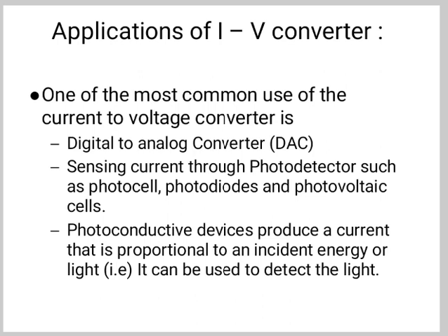Second is measurement of a photoresistor. This type of circuit is used to measure the photoresistor. In dark condition the resistance is very large. As the intensity of light incident on the photoresistor is increased, the resistance decreases. So first the output voltage is measured with a DMM.